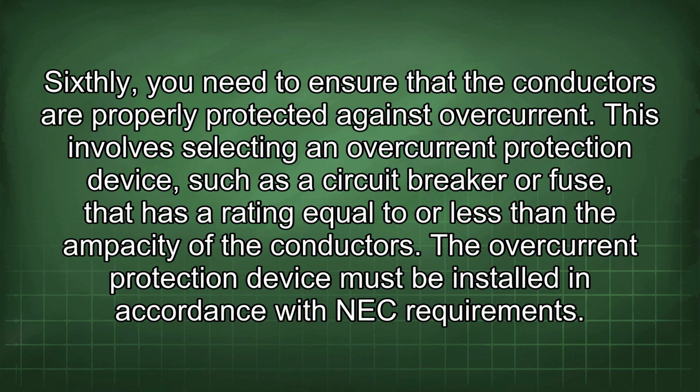This involves selecting an overcurrent protection device, such as a circuit breaker or fuse, that has a rating equal to or less than the ampacity of the conductors. The overcurrent protection device must be installed in accordance with NEC requirements.